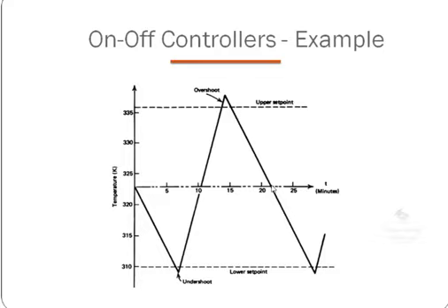So what is the drawback you feel with this on-off controller? We cannot keep the temperature at a specific point. Yes, good. Then? Sir, we cannot get the desired output. Yes, good. See, we cannot have the exact set point. We cannot reach the exact set value. Definitely, it will be swinging between two particular values around the set point. We cannot exactly get what we require. So that is the drawback of this on-off controller.